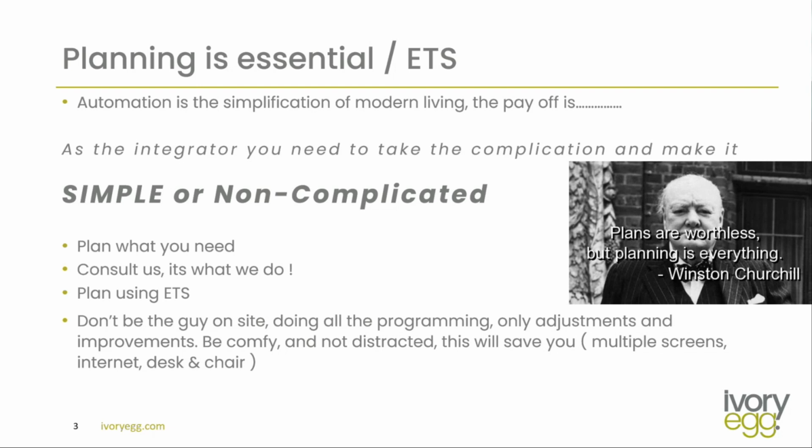Don't forget, ETS is a really good planning tool. I'm going to show you a little bit, but if you can load your project into ETS before you've even quoted it, you can get things like board width modules, how much space you need in a switchboard, and calculation of consumption of your bus devices. And you can do so much out of ETS already. From ETS, you can create a report that will give you a list of materials, basically a bill of materials, of what you need. And you can send that off to get quoted.